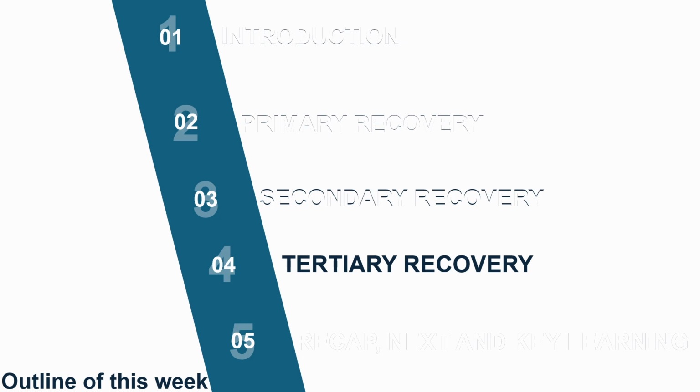Now we move into tertiary recovery, also called enhanced oil recovery or EOR. At this stage, a large volume of oil still remains in the reservoir after primary and secondary recovery. The remaining oil may be trapped because of capillary forces, poor mobility ratio, high viscosity, or bypassed flow paths. EOR methods are designed to target these more difficult remaining barrels.